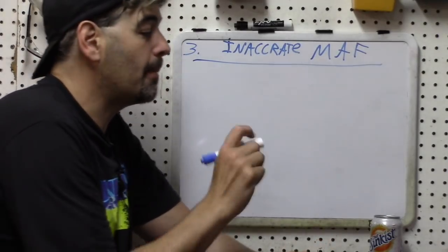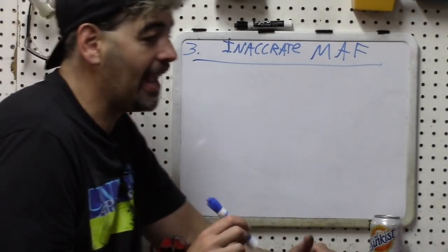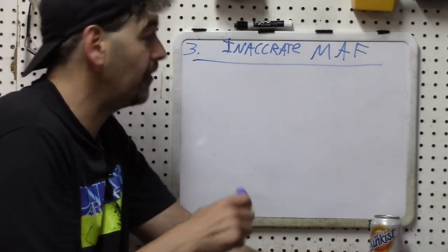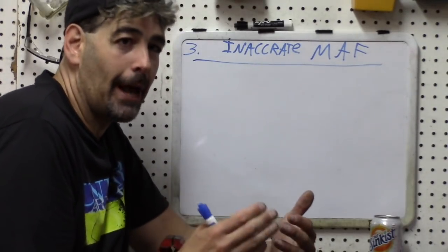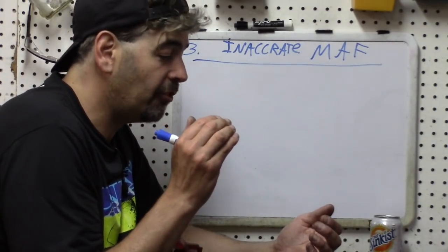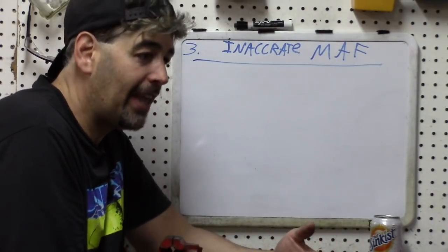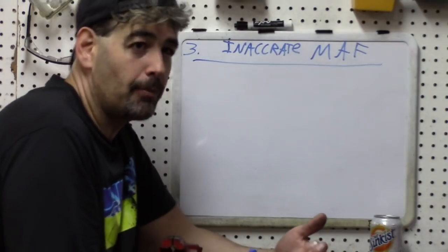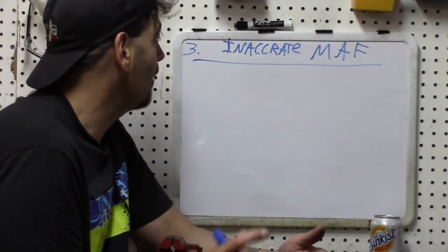Where almost certainly the MAF sensor itself is not the problem, possibly in the case if you've got too high of frequencies or too high of voltages, we'll talk about that. But obviously your possibilities are, with the case of your frequency or voltage, it would either be below specification or it would be well above specification. Below specification, far more common, so we'll cover that second.